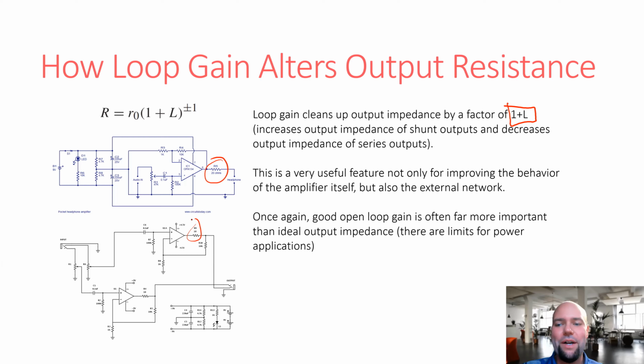Well, of course, if you plug a power plug into an audio jack, you're shorting the terminals of the audio jack. So there's this problem of you never know what idiot with a PhD might be plugging into the audio output of your amplifier. So they'll add these resistors, a way to make sure that even if some idiot plugs a power plug into the output of your headphone amplifier, it doesn't destroy the amplifier, it doesn't destroy the op amp.